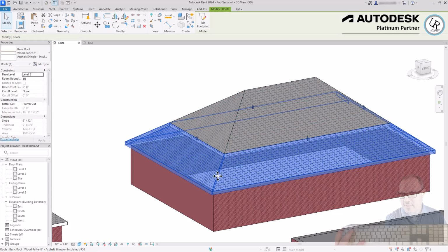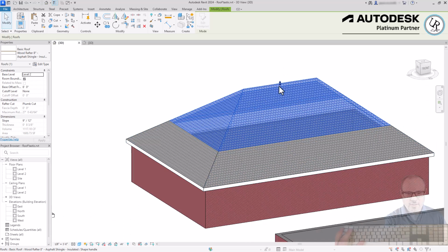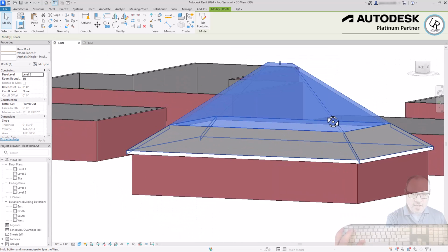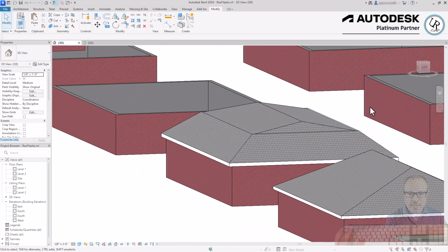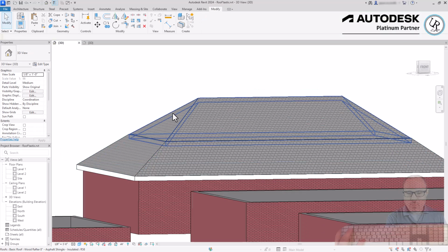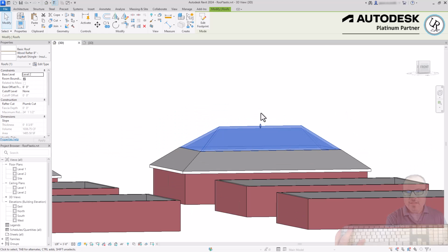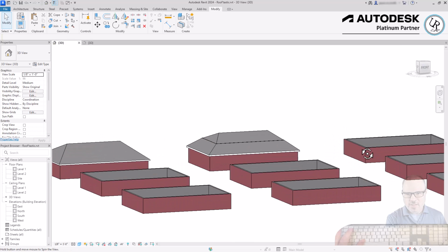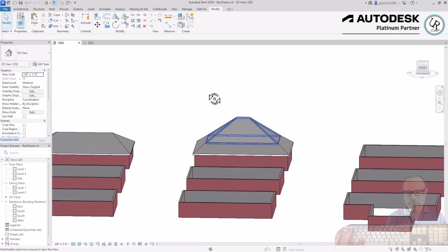Right now, they both actually have the same slope, so they're exactly the same height condition. But what I can do is change the slope of this so it changes the ratio between them, and it gives you that difference in the roof height so that you can adjust them individually. In some cases you may actually need to realign the outline, but some of the compound roof conditions do require some additional roof design included. It does not have very complex tools that will let you create very complex roof conditions without some extra modifications of the roof design.